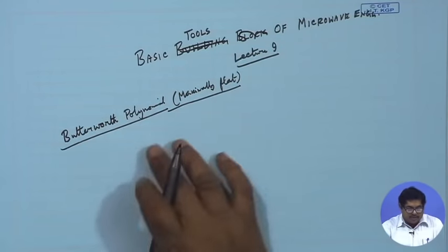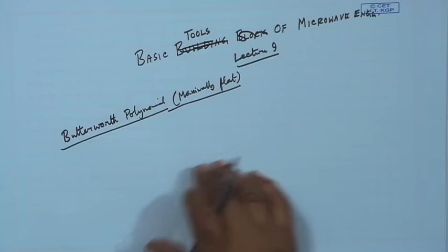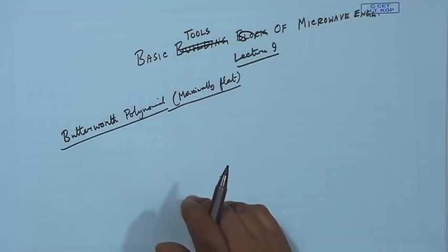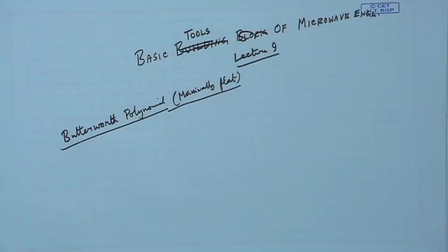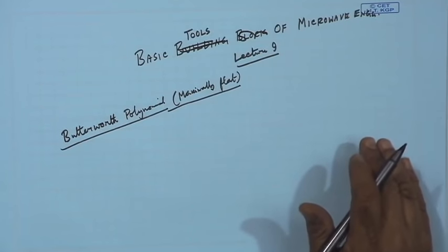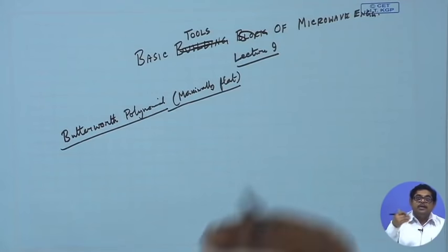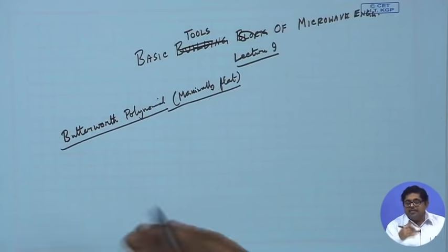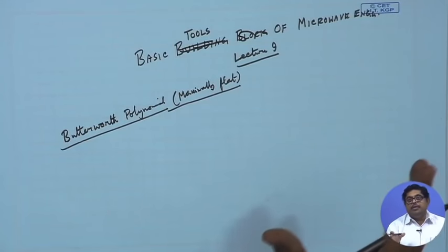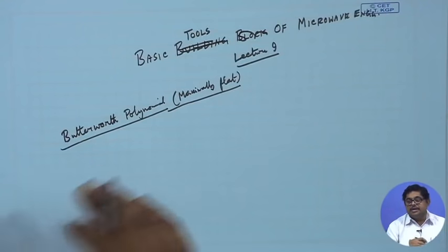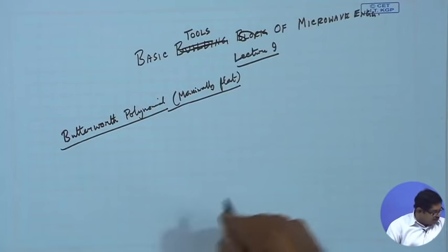So, this is the flattest possible pass band. That means, if we specify the insertion loss in the pass band by a Butterworth filter, then we can say that we will get a very flat response which is desirable in the pass band. Obviously, attenuation constant 0 always cannot be achieved, but we will achieve a very flat pass band, and by specifying a level we can say that okay, I am not attenuating the frequency components in these bands more than this amount.